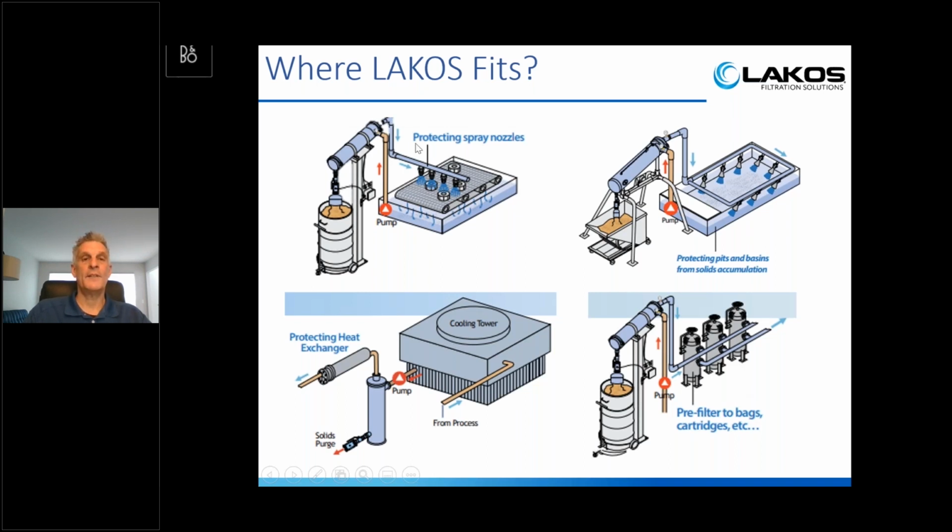Now, when it comes to protecting spray nozzles, like I said earlier, it's very critical that the spray nozzles always get consistent flow and pressure, which the separator is always going to be able to give, because the separators require no cartridges or screens to blind off.